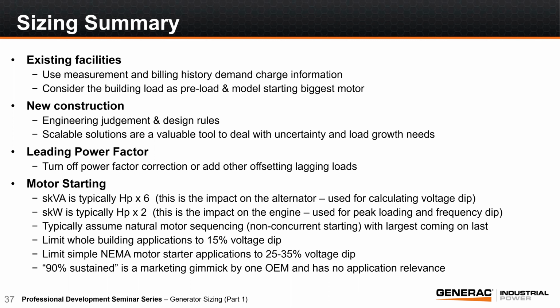But if you've got to start adding additional distribution or beefing it up because you only put in a 2,000 amp panel or distribution, and you need 3,000 amp or whatever the size is, now you've got to shut the whole place down. All right. So you make sure that you're planning the distribution for expansion, even if you're not adding the generation until later.